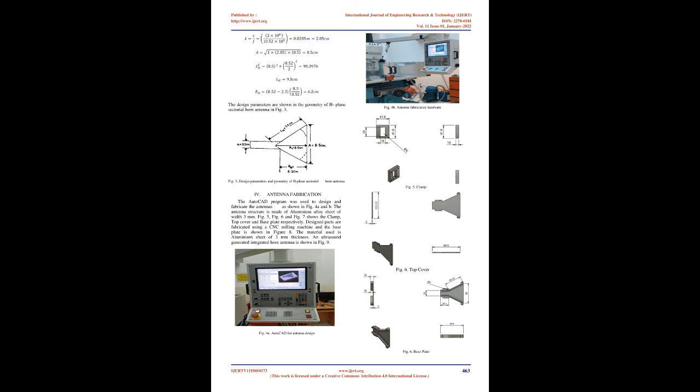The radiation pattern of a sectoral horn antenna will depend on A, the dimension of the horn at the opening, and R1, the length of the horn, which also affects the flare angles of the horn, along with B and A, the dimensions of the waveguide. These parameters are optimized in order to cater to the performance of the horn antenna, and are illustrated in Fig. 2. Calculation of design parameters.